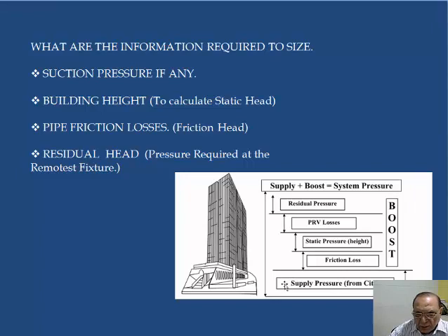This thing may sound new to you, that is supply pressure. In many countries, from the public mains, water is directly supplied to the buildings at a certain pressure, that is known as supply pressure, and it is deducted from the total head required because that pressure will always be available to us. So when we are having a supply system from the tanks, this will not be applicable.